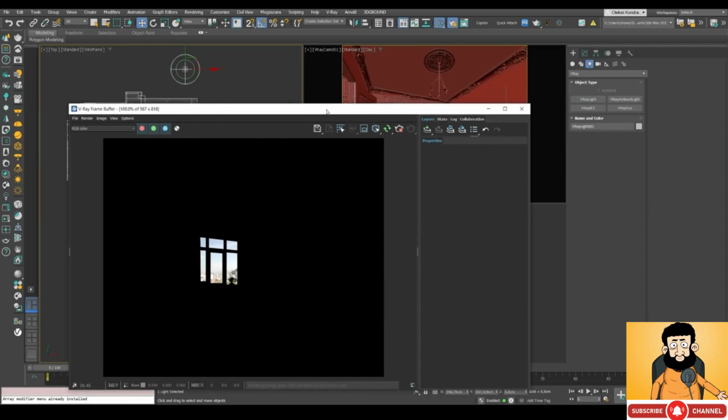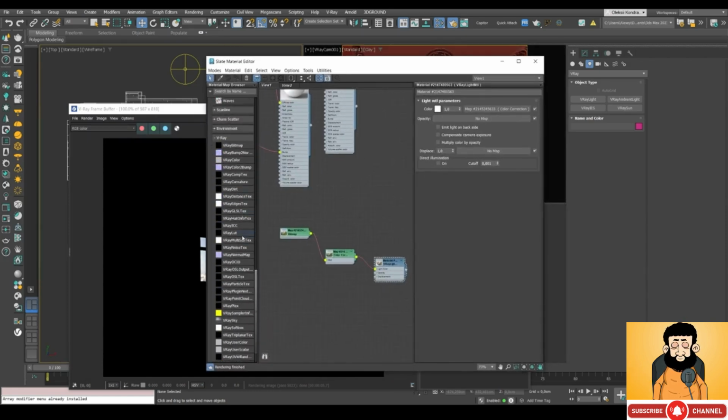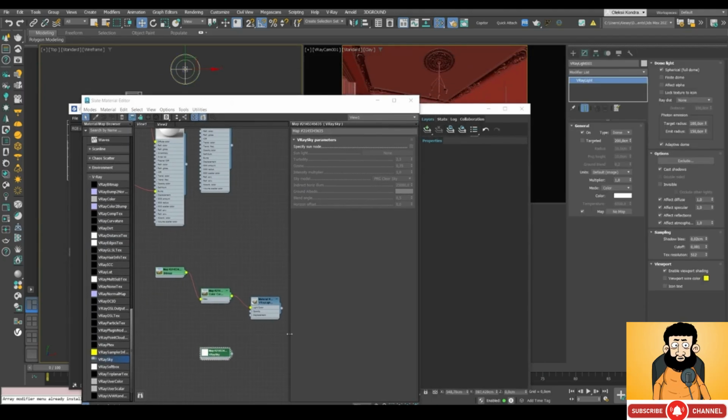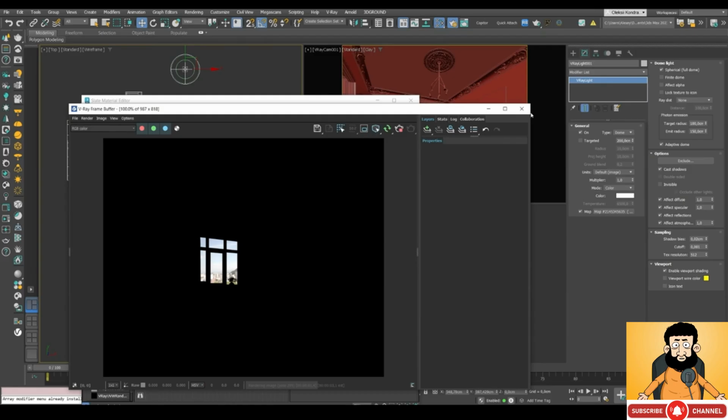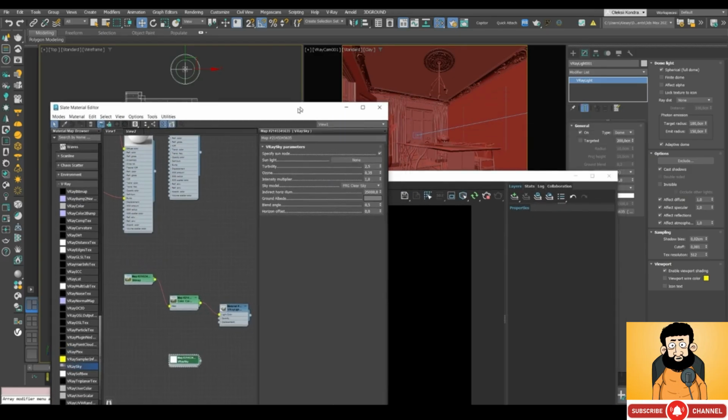So I've got V-Ray dome set up. Next, I'm gonna put V-Ray sky on its map. Select it under V-Ray sky, drag and drop, and connect it on the light source in the map slot, and then select instance. Then we need to check specify sun node box, because we're gonna control the light source with the sun.